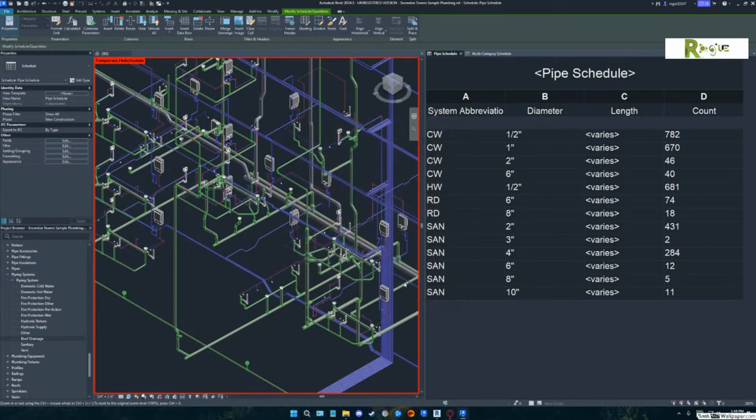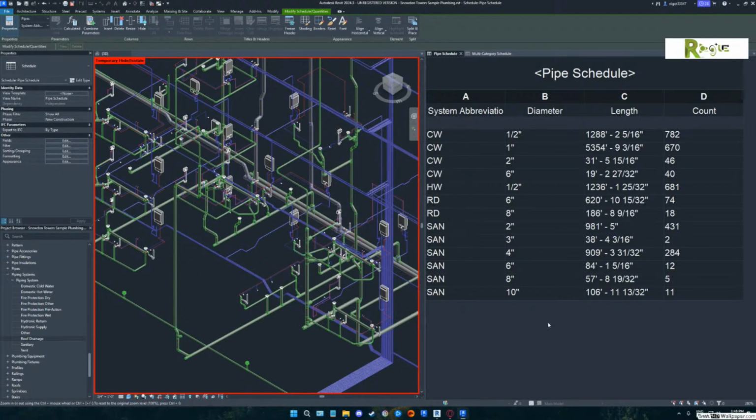Now, this tells you that you need 1,288 feet of 1/2 inch pipe if you were going to pipe it exactly as they do. This would give you some areas where you could start to do quotations. Really, a BIM guy should start helping those people in takeoffs, because you would be amazed at how they actually go figure all that stuff out. But you realize you can figure it out.